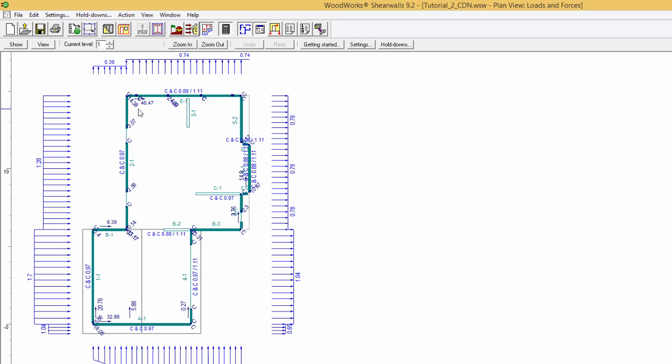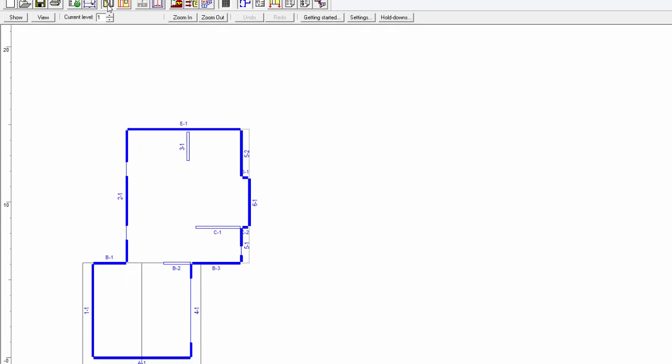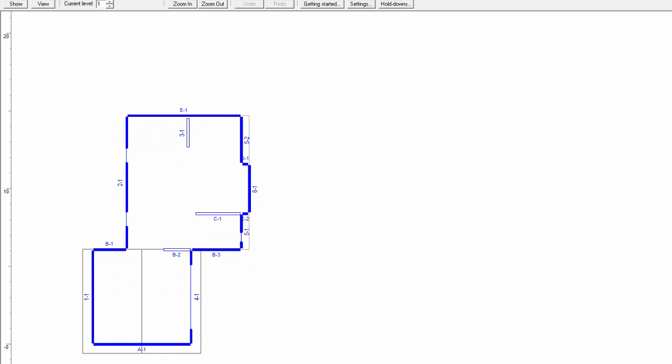Now, in order to remediate this situation, the properties of the walls will be changed by going back to the Walls view. Since the Design and Group option is selected for the exterior walls, applying the change to one wall will apply it to the rest of the exterior shear walls. We will increase the sheathing thickness and reduce the nail spacing for both edge and field, for both the top and bottom levels.